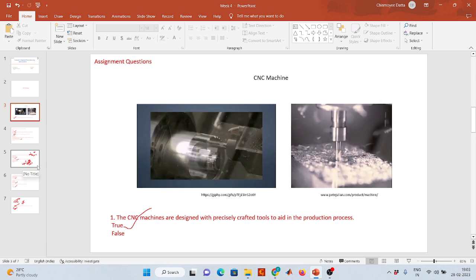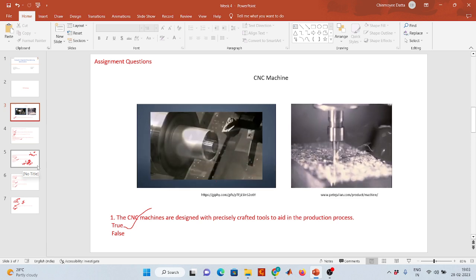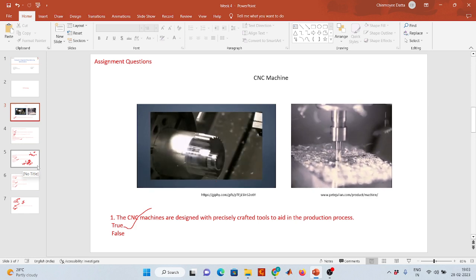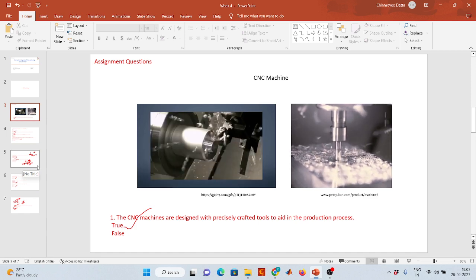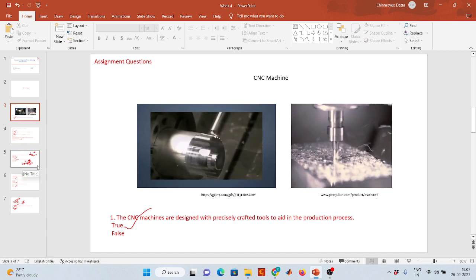But generally, in the aircraft industry, when we do titanium machining, we always use flood coolant. That discoloration will not be allowed.